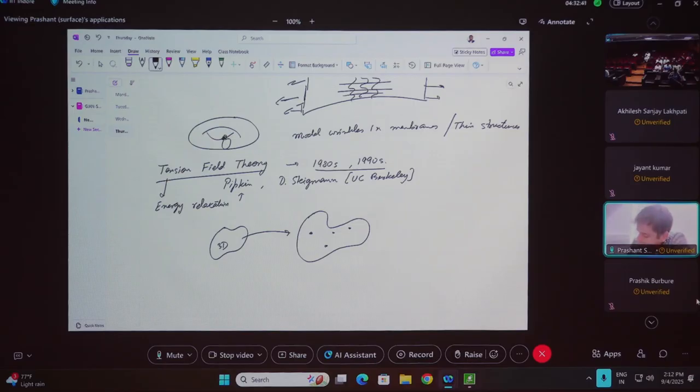And then when we say that this deformation is given by this deformation gradient F, the elastic energy stored is W as a function of F. Okay? And the eigenvalues of F, if I choose the eigenvectors correctly, are lambda 1, lambda 2, and lambda 3.